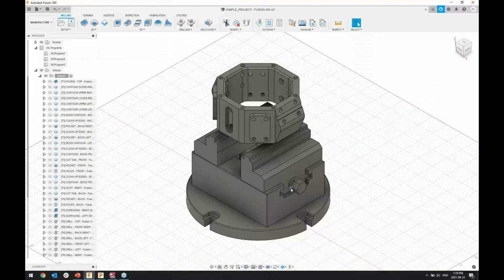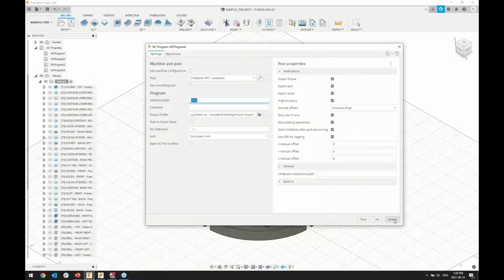At that point, from a programming standpoint, everything basically stays the same. There is no customization whatsoever on the CAM system side. The programming effectively continues the same way you have been programming up to that point. The first major difference that you're going to see is that instead of post-processing for a particular machine tool, we're going to transfer that entire project over to TruePath, so that we can do the code generation, do the validation of that code, and fix any issues, would there be any issues to fix.